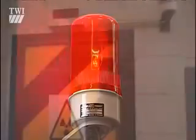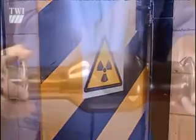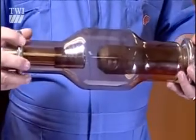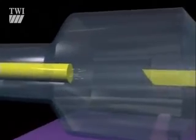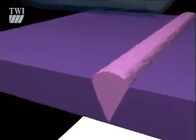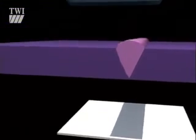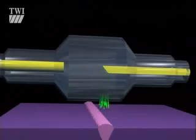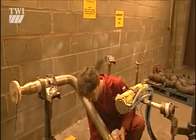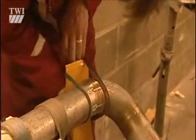Now, radiography is an entirely different type of non-destructive testing. X-rays are produced by directing a stream of high-velocity electrons across an evacuated chamber against an angled target material. The X-rays pass through almost every material and can be detected by a sensitive film on the other side. However, a high-density material will absorb X-rays, while low-density materials allow a greater proportion of them to pass through.